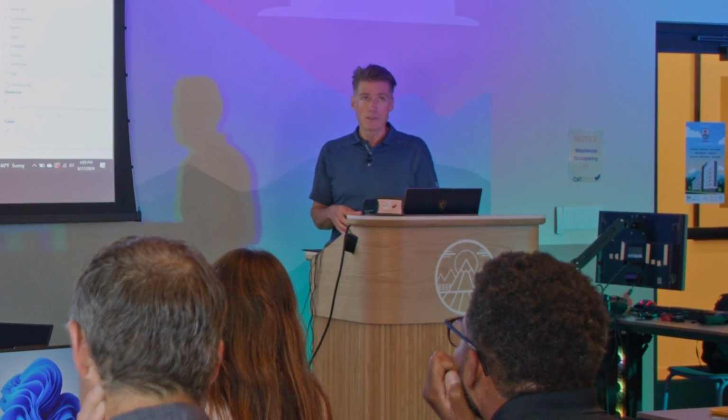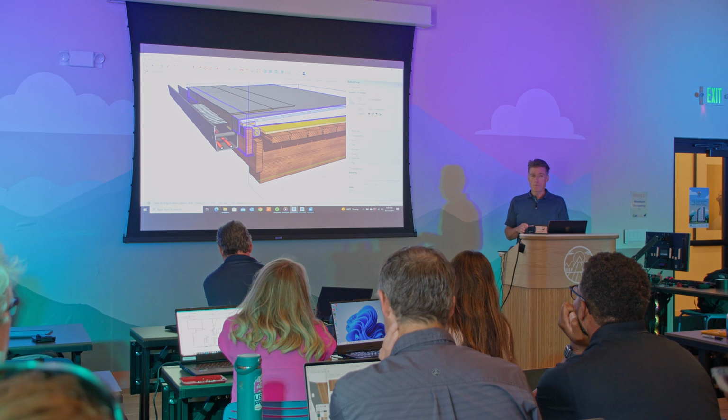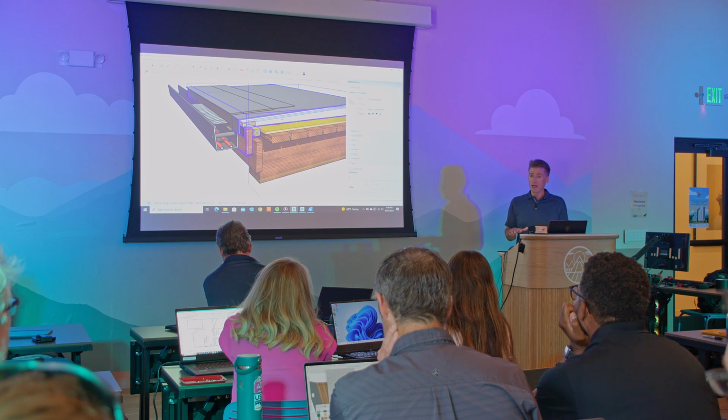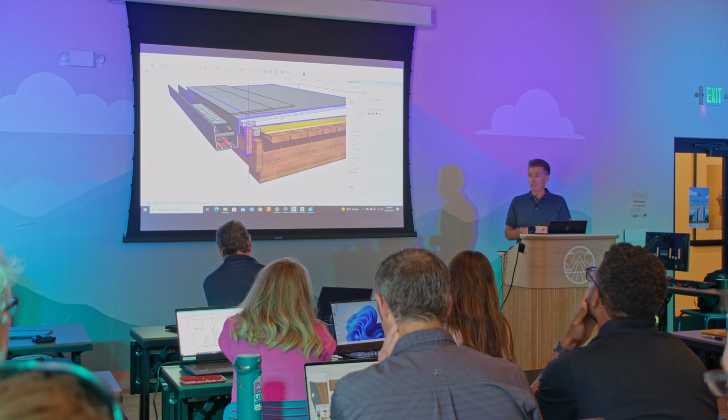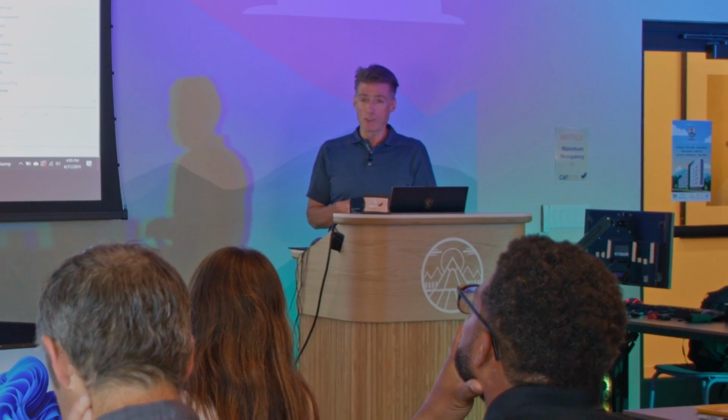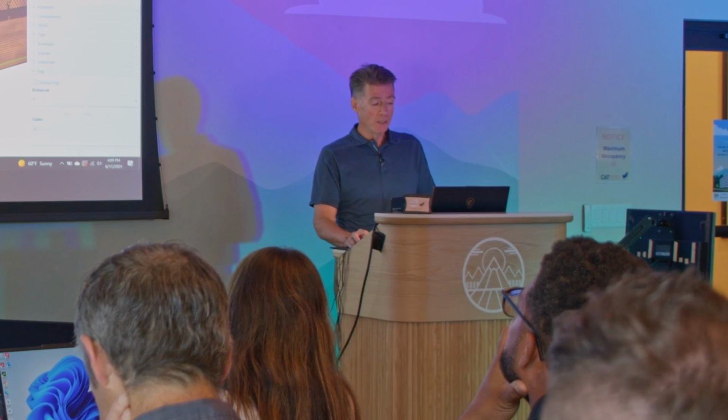For instance, that last house, the first one I showed you in the earlier morning, has a lot of these flat roofs, where we use a PVC single ply system. It's expensive, but it really works well in snow country. We also put a lot of times a ballast on it if it's required by the homeowners association.